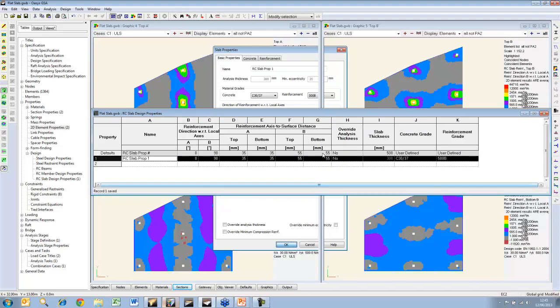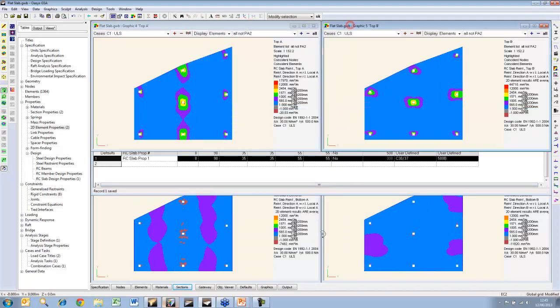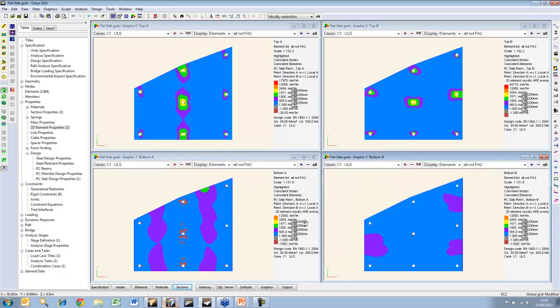And we'll see then the charts are giving us the minimum area steel plus the patches where you need additional. You can see these brown areas here. This is compression reinforcement steel, even with the 300 slab. Only in small patches. Something to watch out for in that central strip.